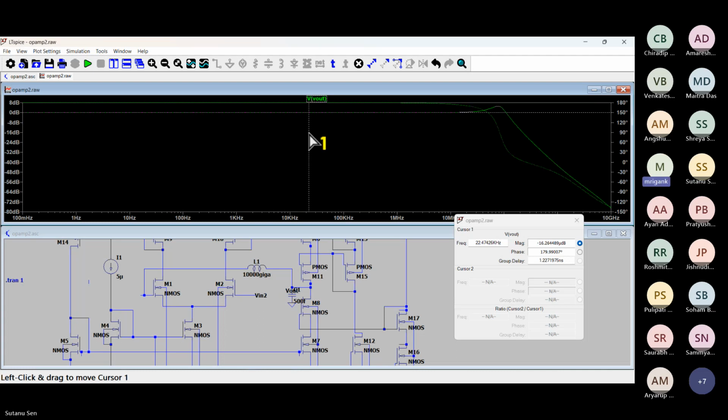I was expecting that even for small frequencies, the impedance omega L will be very high and it will act like an open circuit, but that is not happening. So that means it is 0 dB gain, unity gain. Unity gain is not expected here because L will be open circuit, but that has not happened. Maybe if we change the DC bias of V in.